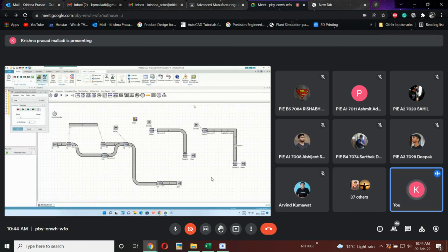So that is what exactly you want to do for today. Practice this model. Open a new model, and in that create a new frame with n number of machines, maybe 5 machines in one model, 10 machines in a second model, 25 machines in a third model. Finally add all the material handling by using different forms of conveyors: straight conveyors, some R curvature conveyors, angular conveyors. Try to use all those things in your model and practice it.